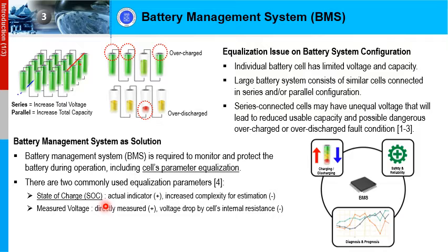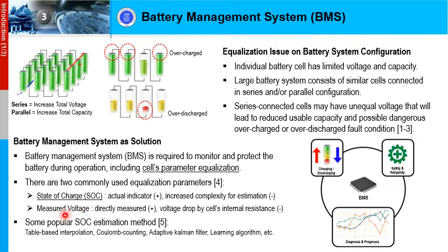SOC is an actual indicator of the battery condition and can be estimated with several methods such as table-based interpolation, coulomb counting, adaptive Kalman filter, learning algorithm, etc. However, in this research, we assume SOC is already known. So we will focus on how the SOC equalization algorithm is developed.